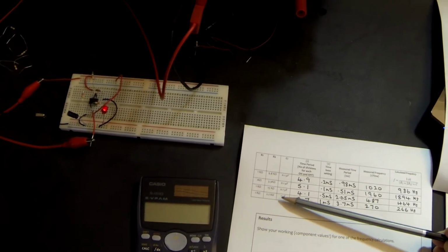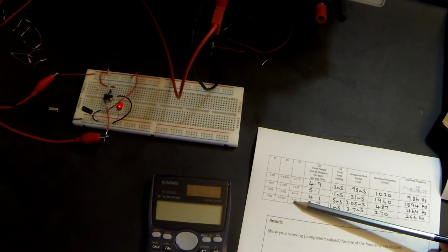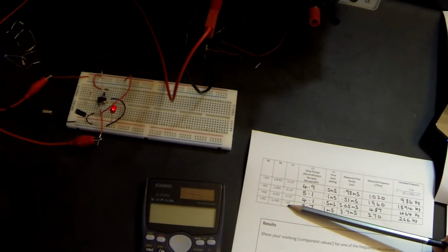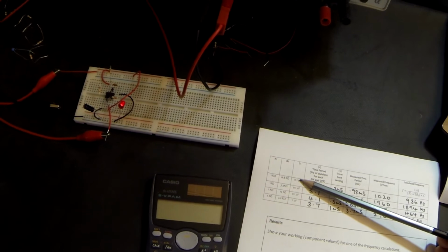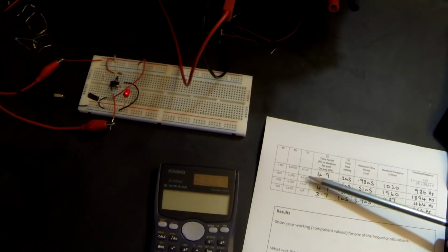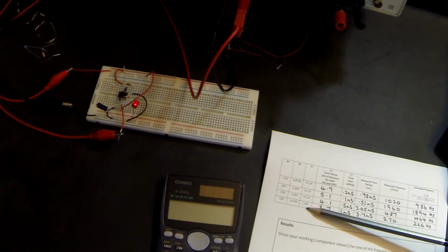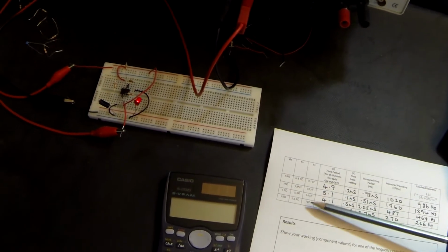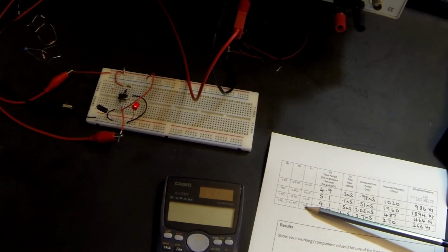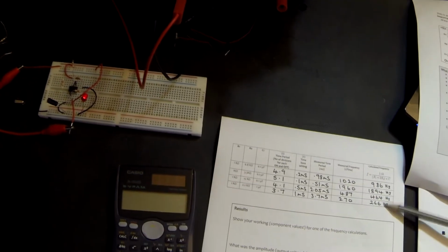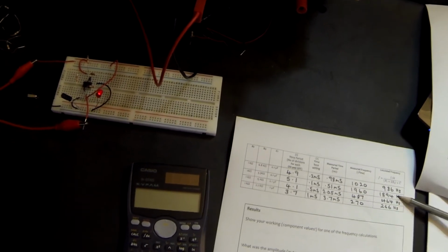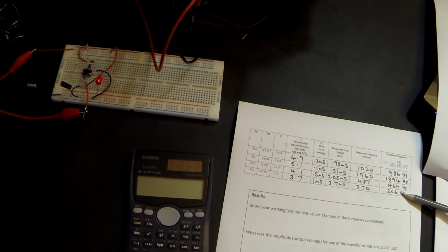And then finally here, even though we are changing not only R2, we are changing C1, but C1 is significantly different. Perhaps that would be the best one. The second and the fourth one, R2 was approximately the same, R1 was the same, but C1 has changed by 10-fold. And you can see here that there's a significant difference in frequency where we have reduced the frequency.